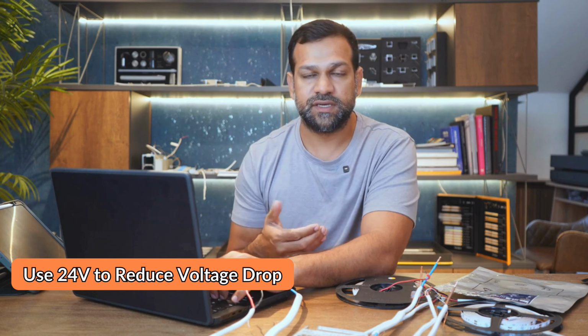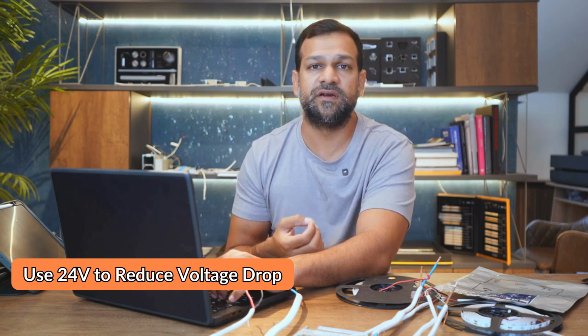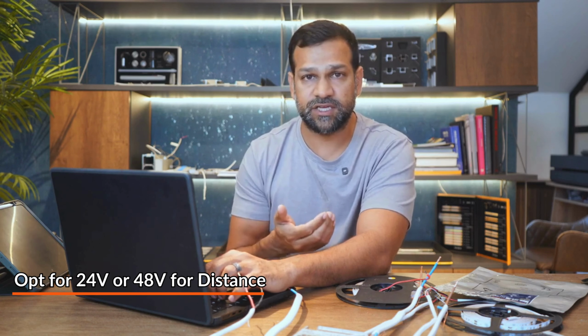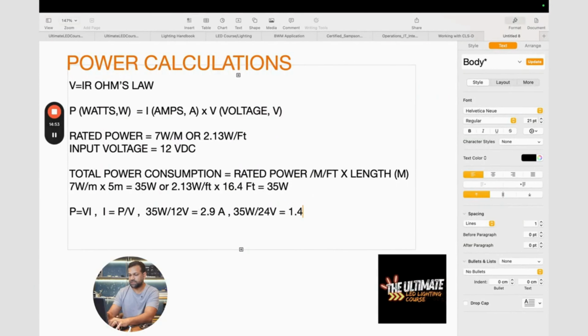In our systems, we tend to use a lot more 24 volts, and that's because there's going to be less voltage drop. So 12 volt LEDs are very good for localized power supplies and cabinetry. But if you're doing linear lights in the ceilings or multiple systems that are far away from the power supply, you want to opt for 24 volts or even 48 volts. So let's look at the calculation and see how the amperage drops. You have 35 watts divided by 24 volts, and you're going to get roughly 1.46 amps. So as the voltage goes up, the amperage decreases.